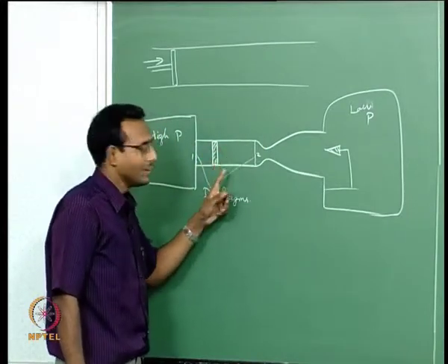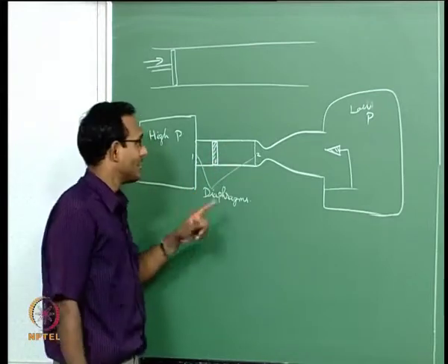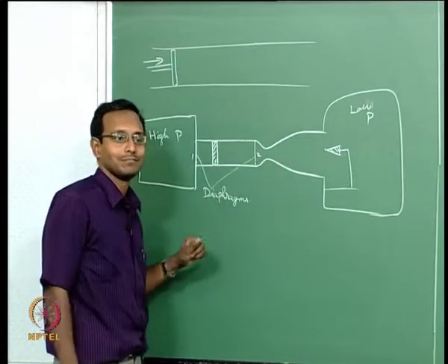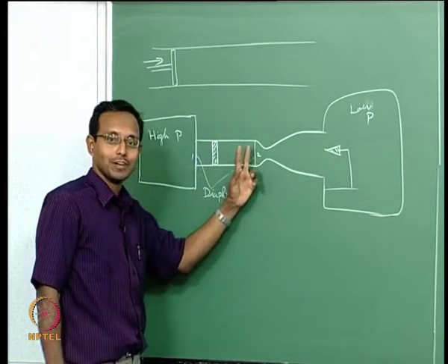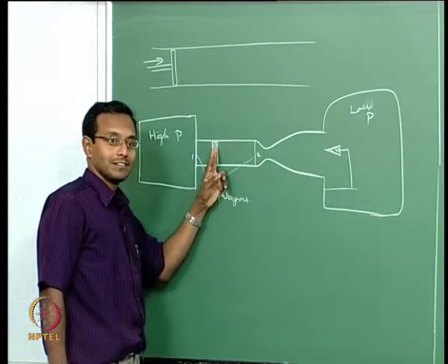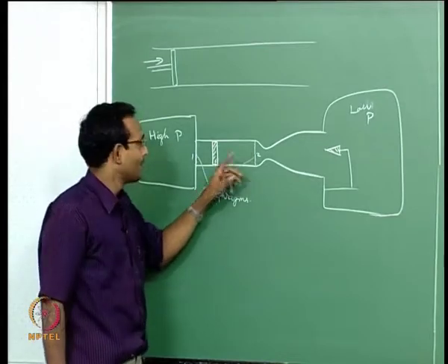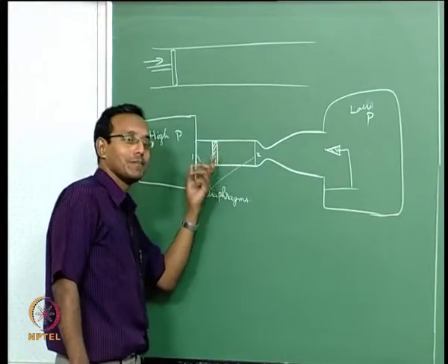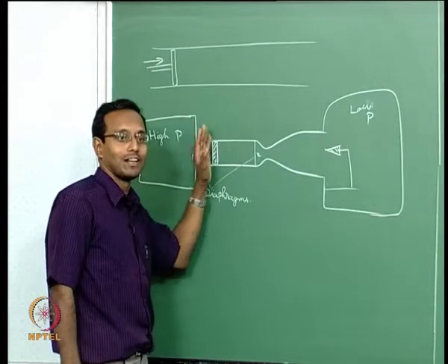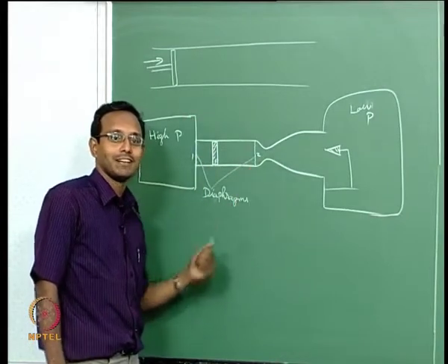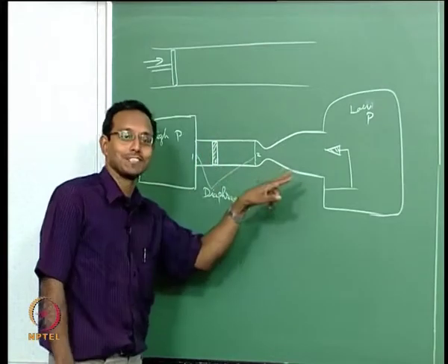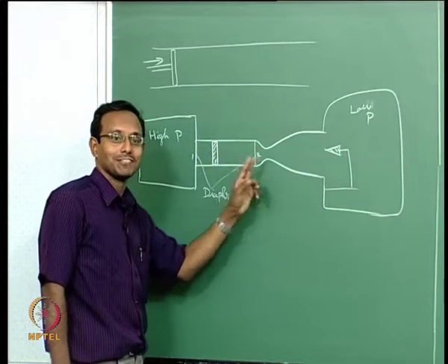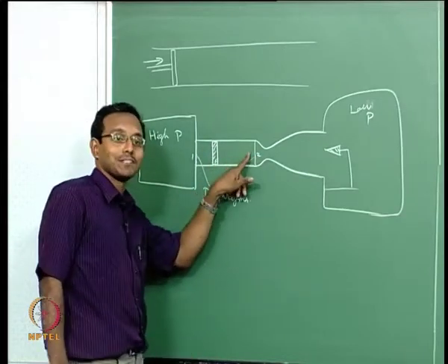While this is moving in, what is happening on this side? There was a shock created. Now, I will say this diaphragm is a little stronger and it can hold a little more pressure difference across. What will happen? It will bounce and come back. When it is coming this side, the flow here is 0 velocity, but the piston goes and attacks that shock now, right. So, now the reflected shock will be even stronger than with a straight sitting wall, and the shock comes and reflects on it, right. So, what is going to happen? I am accelerating the shock even faster, the reflected shock is going to go even faster, and if I wait for some 2-3 iterations of this reflection, I can create really high pressures here.